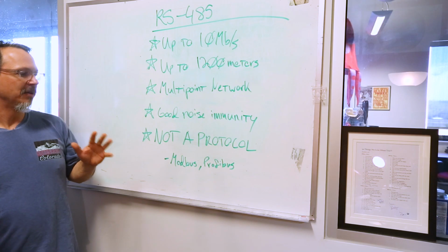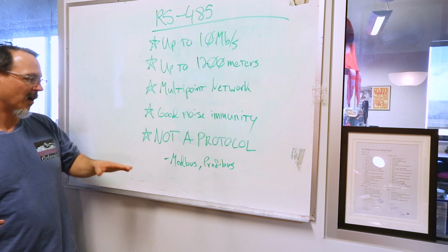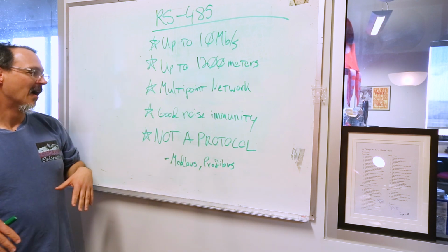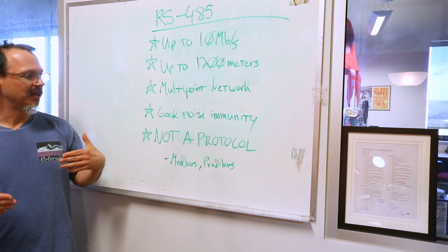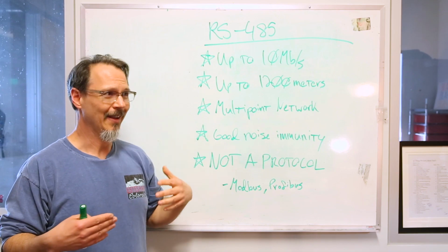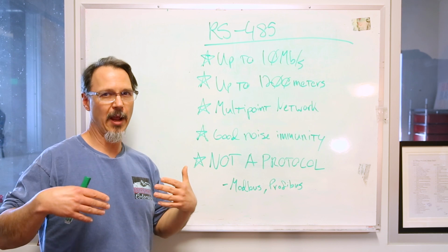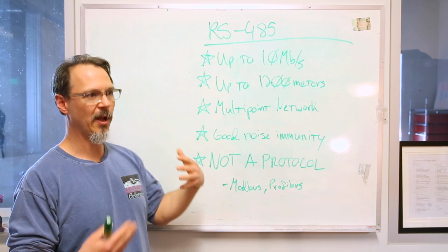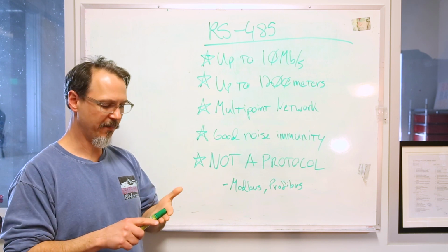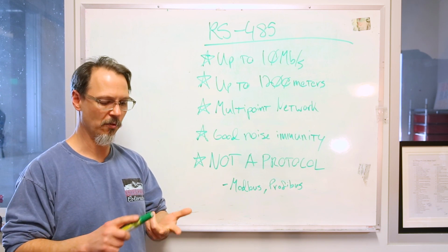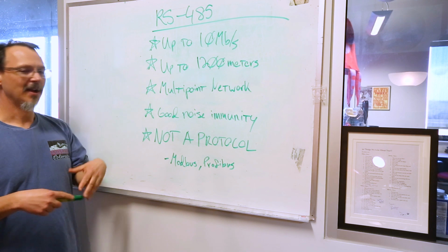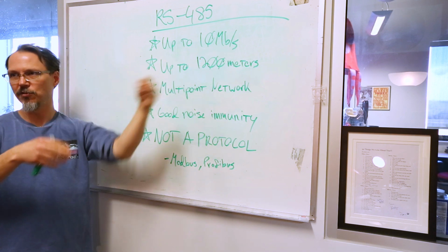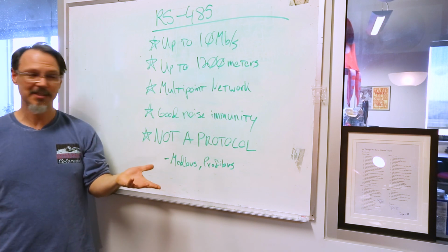Now, some of the protocols that use it are Modbus or Profibus, and I will let you guys look that stuff up. But because of the nature of the signal, it's well geared to serial communication, like a UART. So what you will have is an RS-485 driver or receiver or transceiver, and it shoots out on RS-485 and you talk to it over a UART. So something as simple as that, all right? Cool.